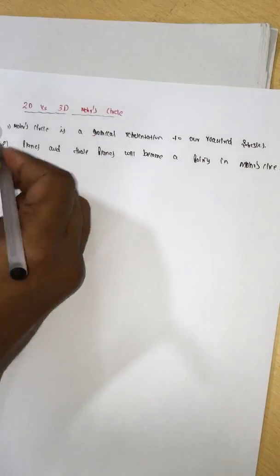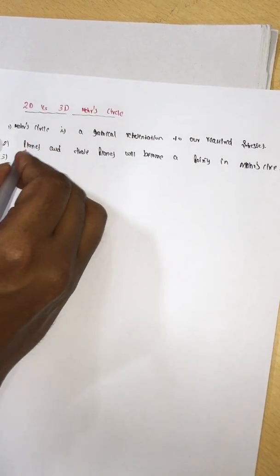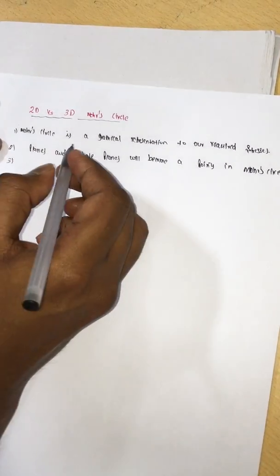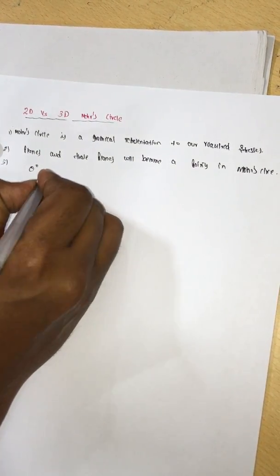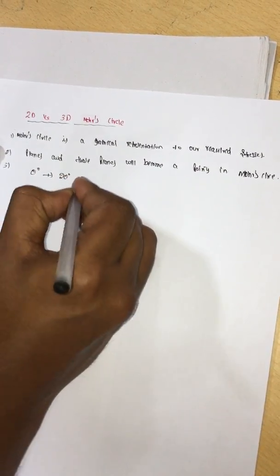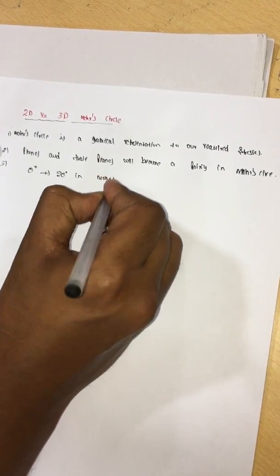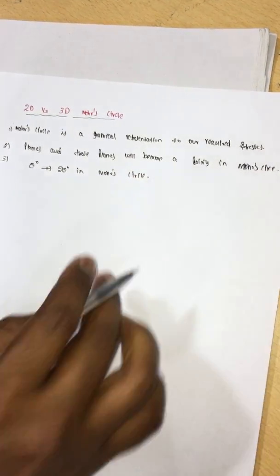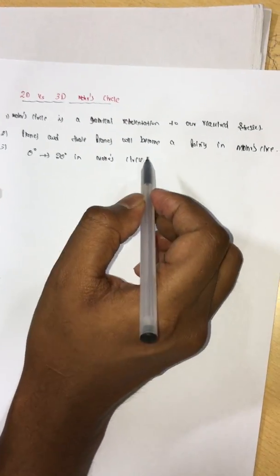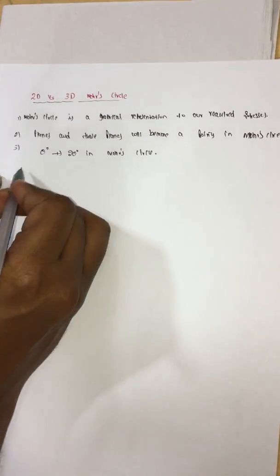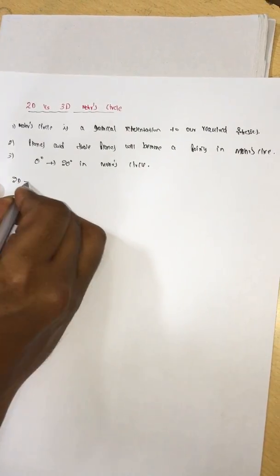Okay, and then if you rotate our plane in that element by theta degrees, then it is rotated by 2 theta degrees in Mohr circle. Okay, as a graphical representation you have to follow these things in your mind. Now let me continue my video with the 2D analysis.